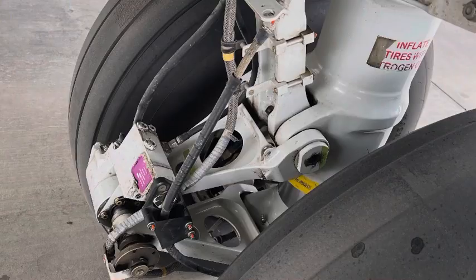One cause of the shimmy damper breakage or failure in the main landing gear is smooth landing. After takeoff, the piston is free to move out from the cylinder, I mean the shock strut, so the piston will extend out, and the amount of the extension is limited by the shimmy damper, because we have two linkages attached to the up and down side of the shimmy damper.